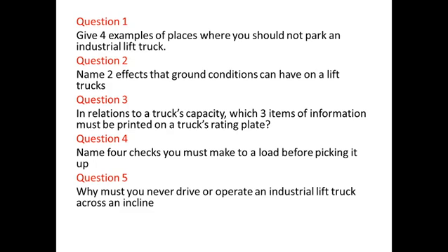Question 4, name 4 checks that you must make to a load before you pick it up. Well, before you pick up a load, you need to ensure that the truck is able to lift the load, so you need to be aware of the weight of the load. You need to be aware of the height of the load, the width of the load, the length of the load. So to ensure that you're not exceeding the load center of the vehicle, and just to make sure ultimately that you're able to transport the load safely.